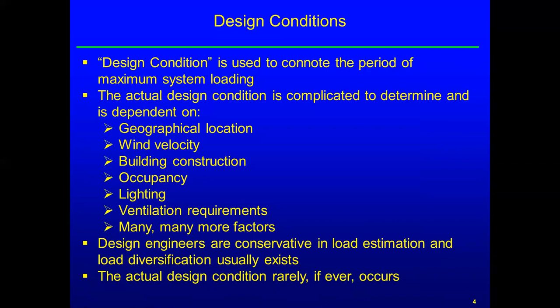And you usually want to be conservative, which means you want to perhaps overestimate the load a little bit, because you'd rather have a system that's 10% oversized than 10% undersized. People get pretty upset when they're not comfortable, when it's really, really hot or really, really cold. Actual design condition rarely, if ever, actually occurs, but it's still important in the design process.